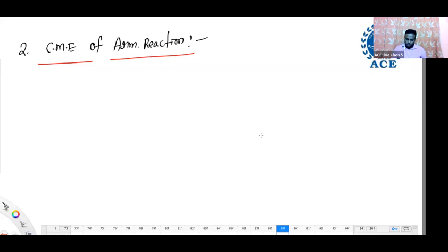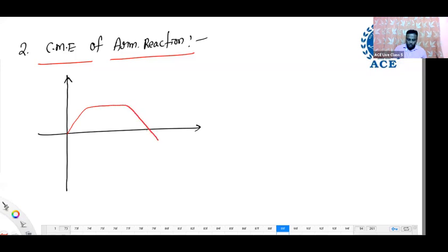See, I will show you here. During the cross magnetizing effect of armature reaction, if it is only main flux like this, what is the flux along the brush axis exactly? 0. The main flux is 0. This is under no load condition. Only main flux is there. Then no spark you will get. No load condition, no spark. But spark occurs only under load operation, because under load, current is there, and armature flux, armature reaction. One of the effects is the cross magnetizing effect.